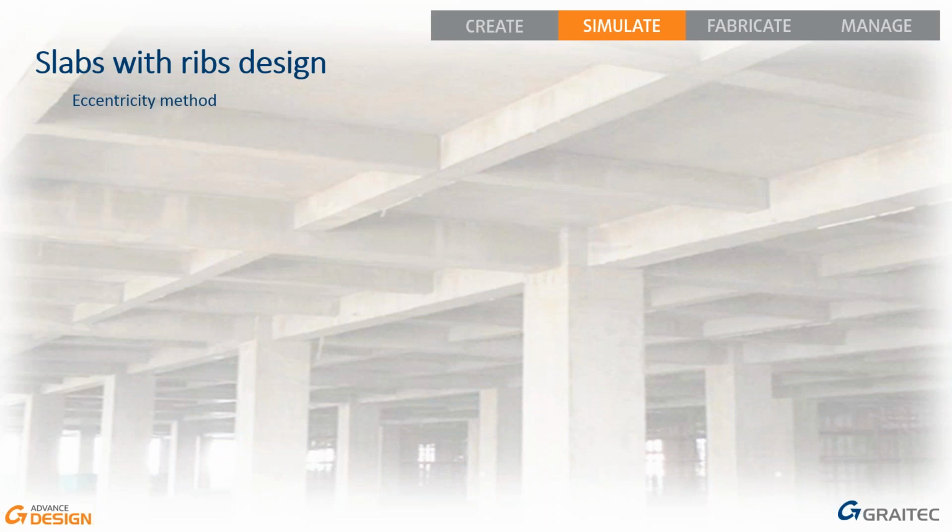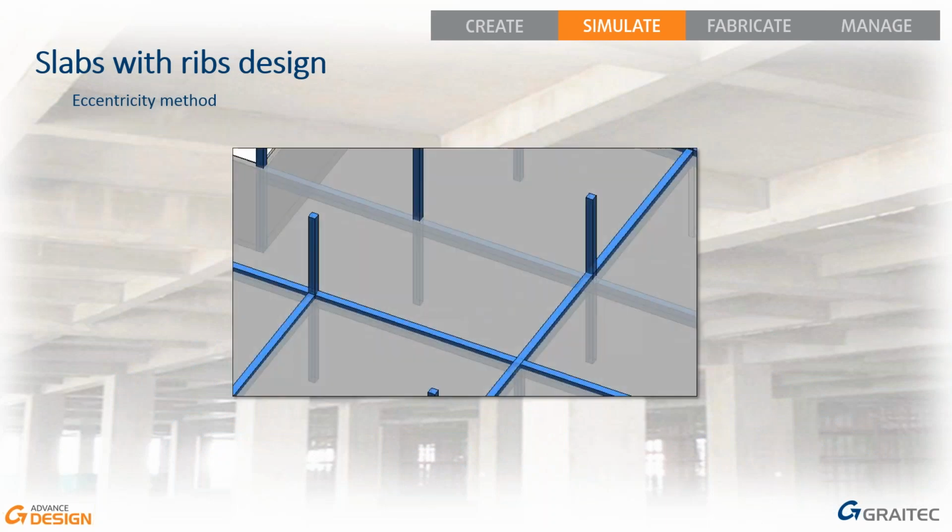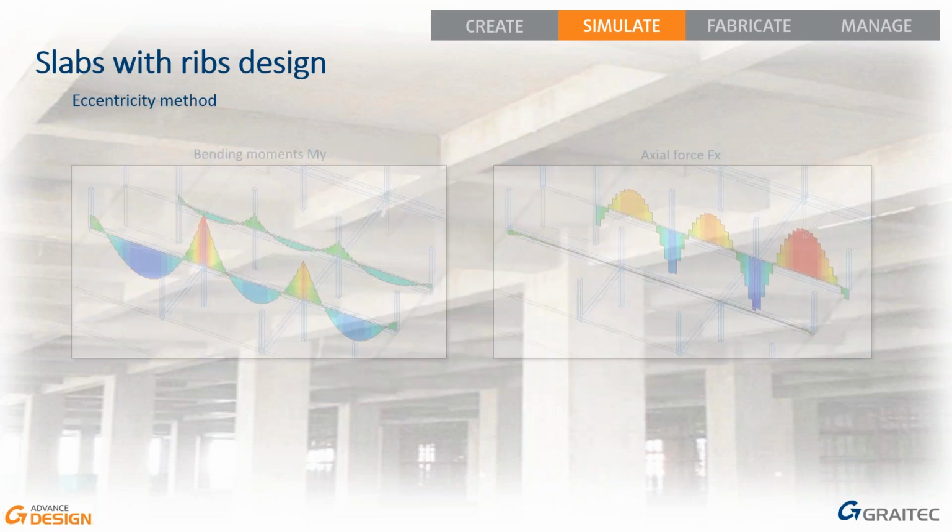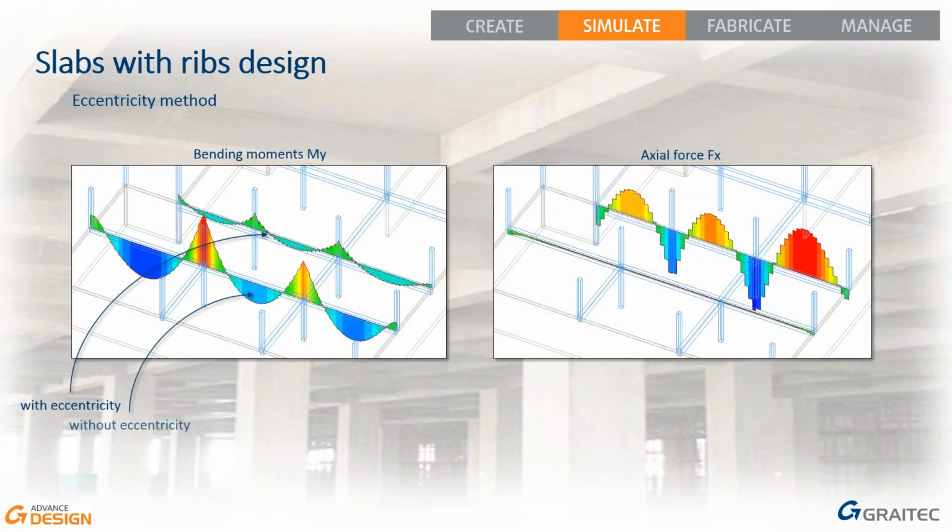So if it comes to the eccentricity method, let's see two beams, one which is modeled by default and one with defined offset. As you can see, the FEM analysis results actually change with the beam with eccentricity. The bending moment is really, really low compared to the default beam. So that's not what we wanted. Our beam is much stiffer now, so we expected higher design efforts.